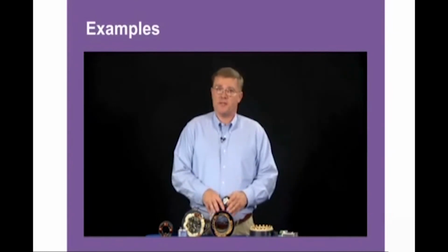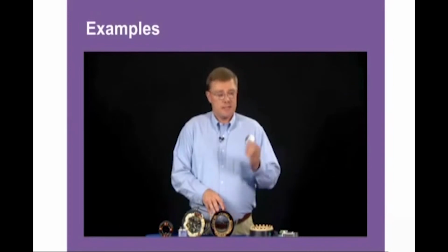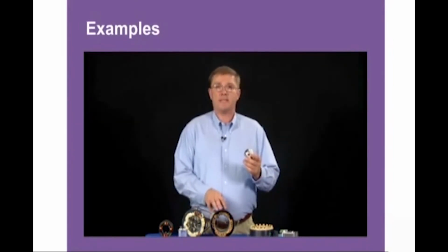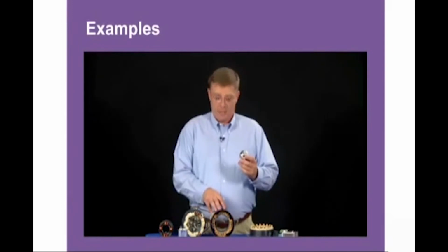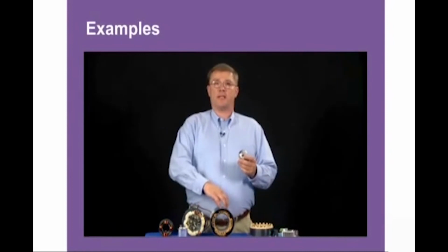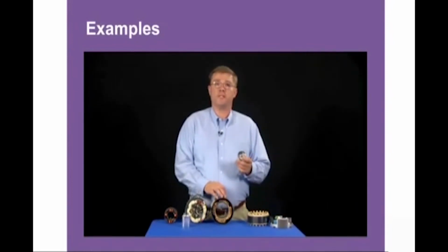There's the standard split phase, then we have what's called a capacitor start motor. Still has a centrifugal switch, is still a split phase motor, but now we put a capacitor into the start winding of this motor. You typically see a doghouse on top of this with a capacitor inside. It's wired directly into the start winding. This allows for a little greater starting torque and a little more efficiency.